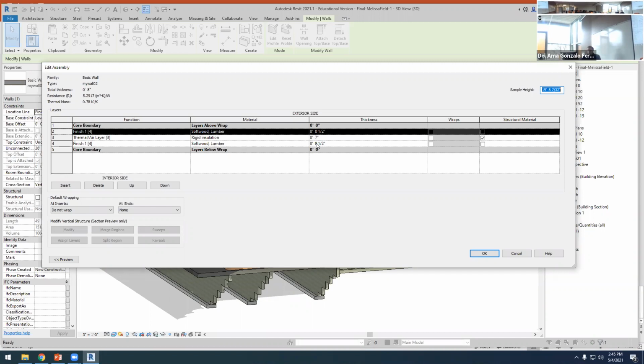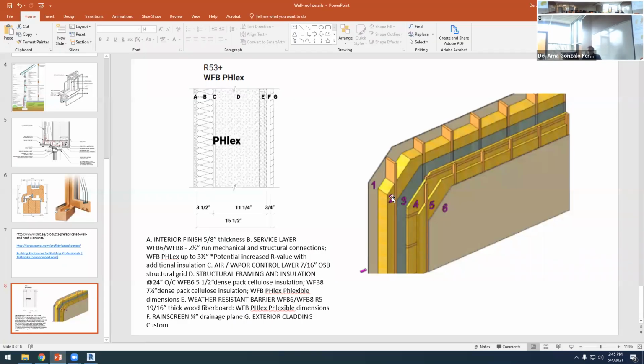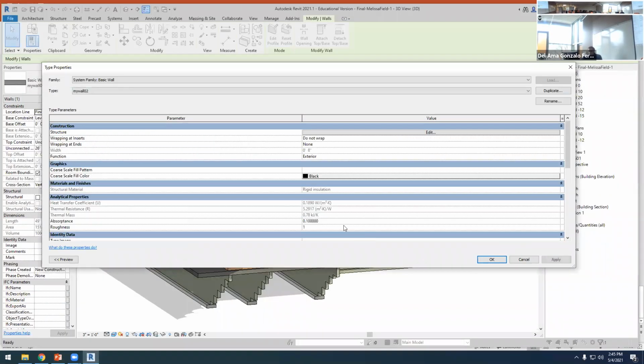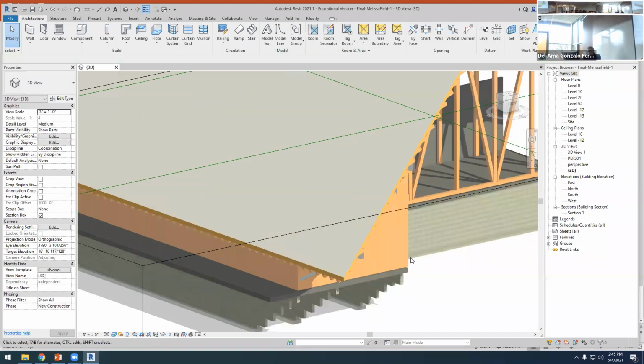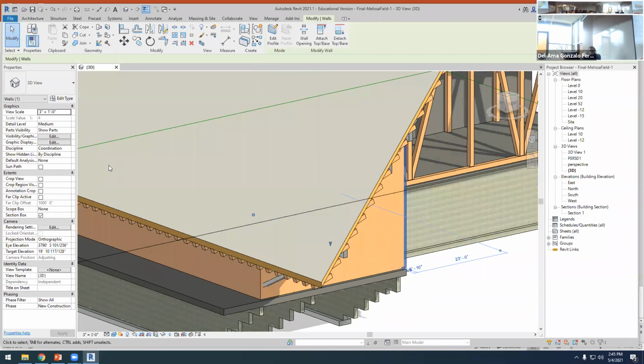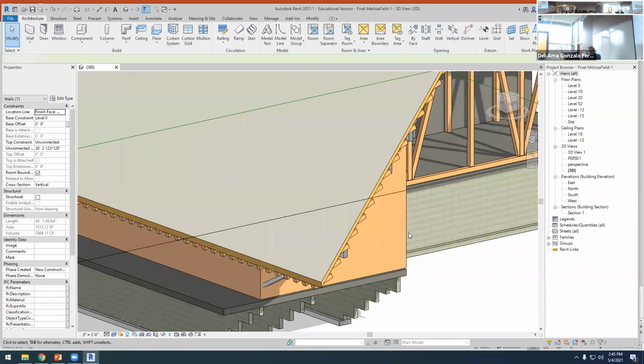I would appreciate that you create the new wall that you're working with. Okay, so if you're working with this kind of wall, and the wood thermal insulation is 10 inches, and then we have 2 extra inches to avoid the thermal breach. Okay, you can do that. Anyway, I'm not going to do it, but I'll check what kind of walls you are working with. Okay, that's fine, but it can be better.